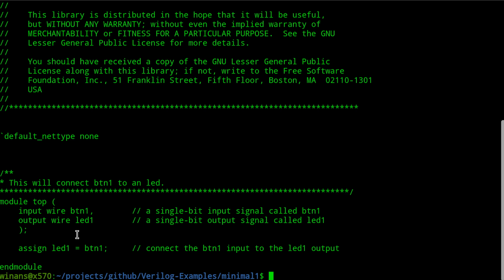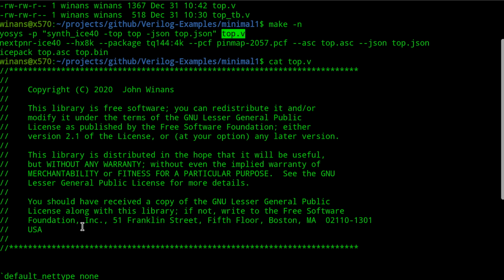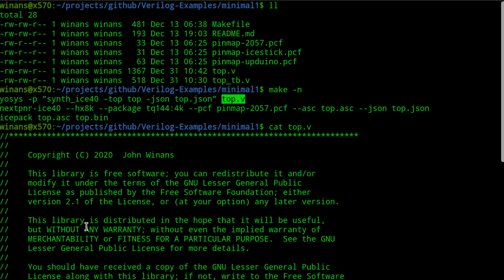Start here, okay? Now, in Verilog, you don't normally have an official name of something. What you do is when you build it, you say, by the way, the top level thing is called whatever I decide to call it. I could have called it XYZ if I wanted to. It's overwhelmingly common to call the main top level module top. Okay? So I'm going to follow that convention. It's very useful, okay? You can always kind of keep your bearings at what you're doing.